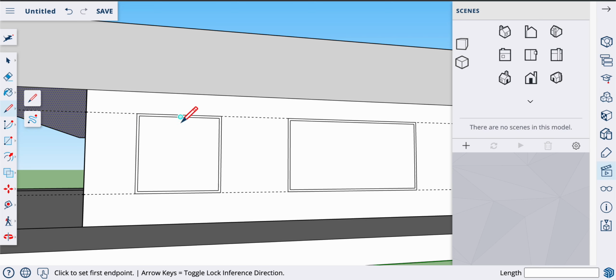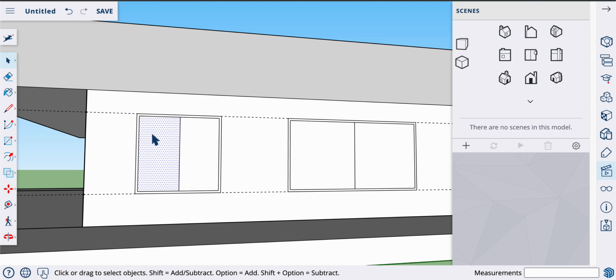If you want to get more technical with our windows, we can put in the window openings. So I'm just going to go through and cut these in, that's good, and then I might use this offset tool a second time to inset those panels. Sometimes you need to actually just click on one and then click back, like that. Now I'm going to set that in 50, yep, and then I'm going to select the next panel.